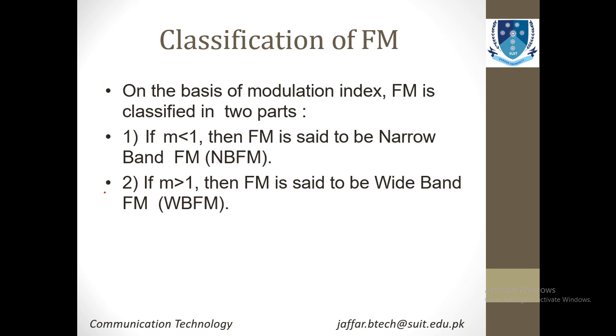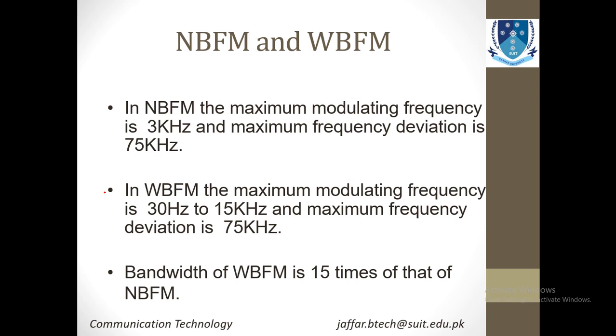Let's talk about this further. So in NBFM, the maximum modulating frequency is 3 kHz, and the maximum frequency deviation is 75 kHz. Means your signal can be deviated up to 75 kHz of frequency.